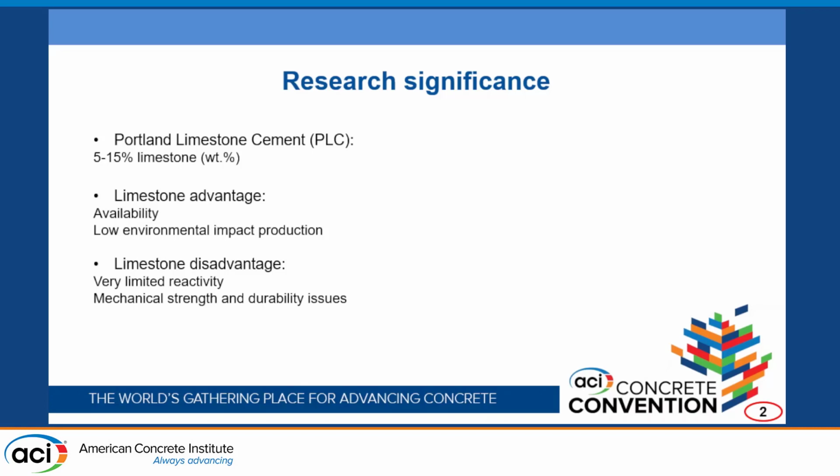One of them would be the very limited reactivity in cementitious media, and also we will get lower mechanical strength and durability when we use a larger quantity of limestone in cement-based materials.